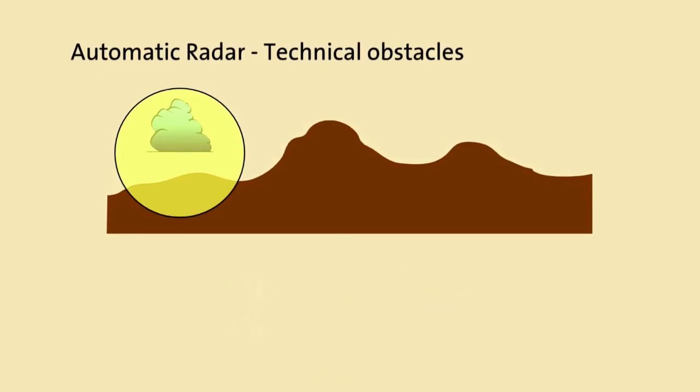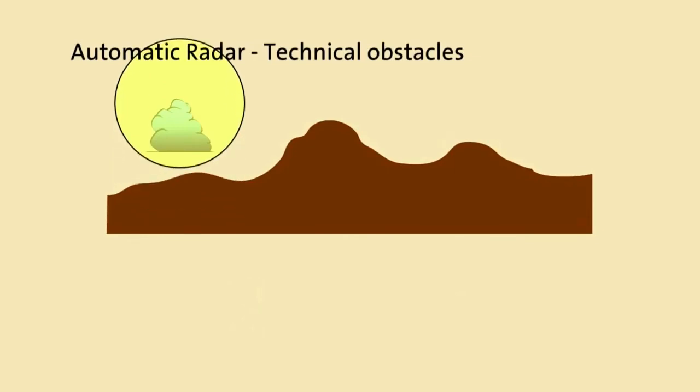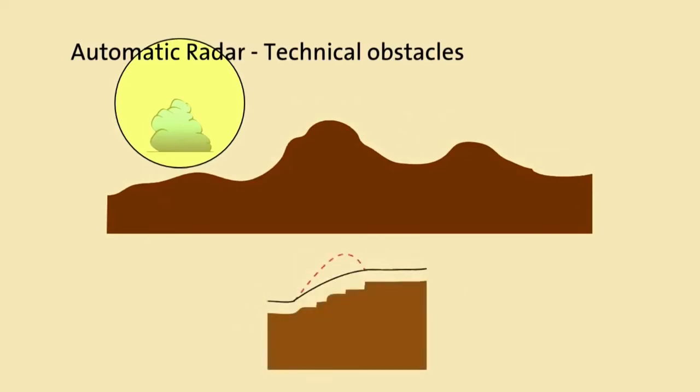When operating the radar manually, one method for distinguishing between ground clutter and weather is to raise the tilt to reduce the clutter. Unfortunately, this also tends to reduce the intensity of the weather return and limit the range that weather can be seen. In addition, with certain types of terrain, such as the cliff face displayed here, very strong returns can show up further out on the edge of the beam and unexpectedly introduce ground clutter into the picture, even with a high tilt setting.